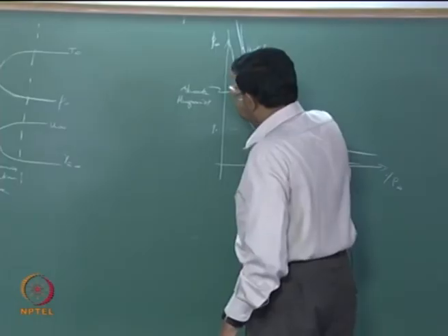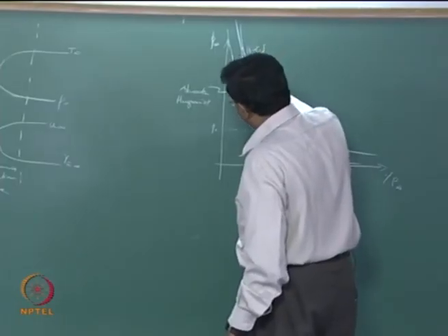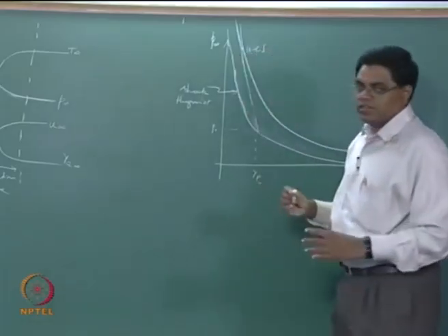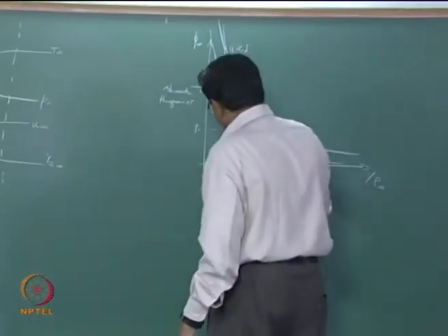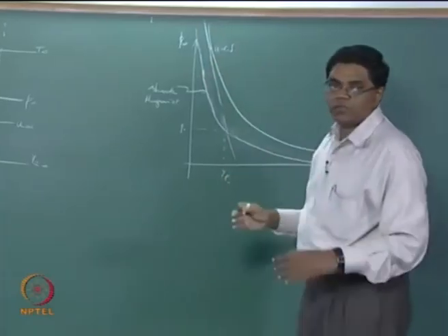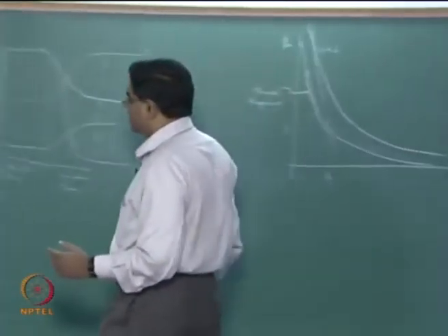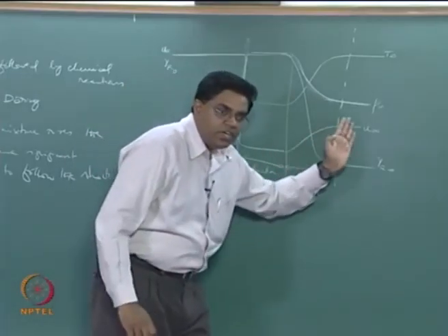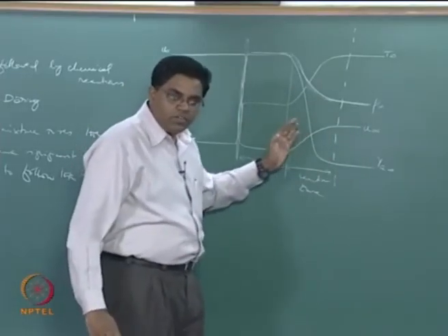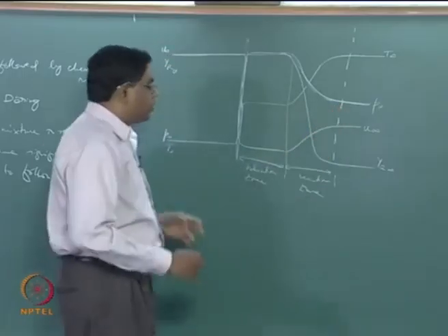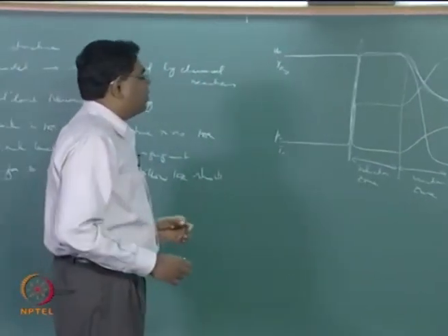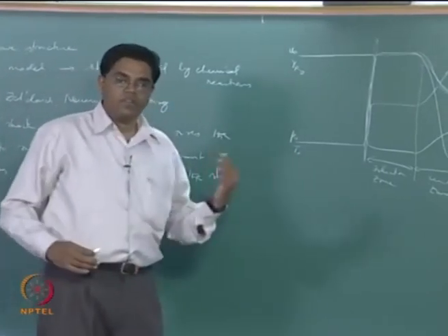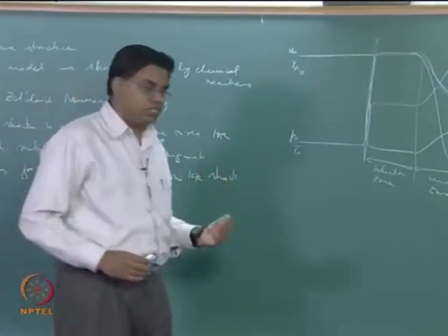But then we are looking for how you are trying to locate your point between successive Rayleigh lines intersecting successive Hugoniot curves for different Q. That means as we go along from here to there, you are having heat release happening, and then the velocity gradient also keeps changing. So what we want to do is look at a Rayleigh line with viscous effects. The viscous effects will now bring the velocity gradient into it.